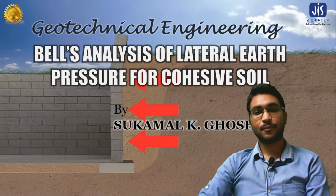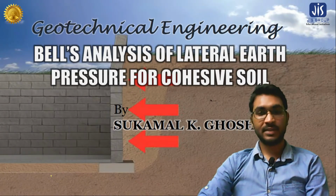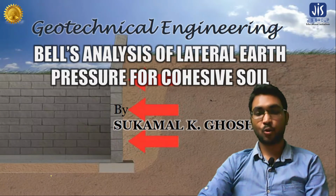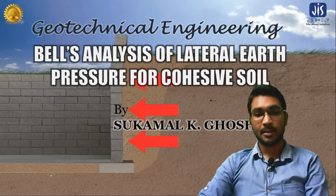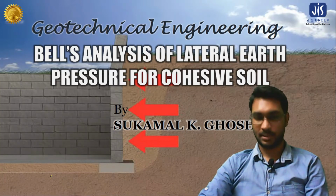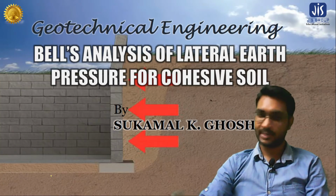Now in the analysis of cohesionless soil, we didn't calculate the passive earth pressure separately. We just replaced the coefficient of active earth pressure with the coefficient of passive earth pressure, and we got the passive earth pressure, right? But in the case of cohesive soil, we need to calculate the passive earth pressure separately. But why? Let's discuss.